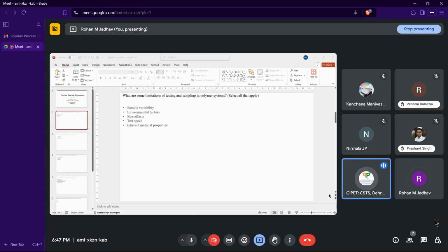Because once you are saying the primary advantage, we are using injection molding for a higher production rate in the industry. So the tool, which is known as the mold, should be a costly one so that it can sustain many shots or cycles. Exactly, so automatically low tooling cost will not be there. But that is basically the initial investment in the material itself.